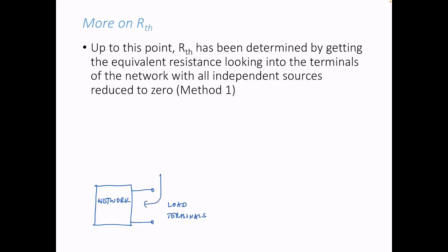To determine RTH with respect to the load terminals, we get the equivalent resistance with all independent sources suppressed. That's the technique we used to determine RTH, no?